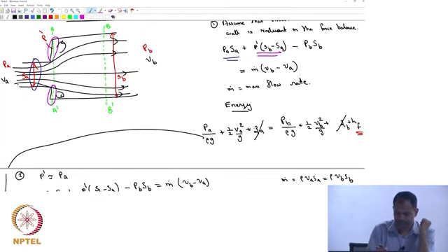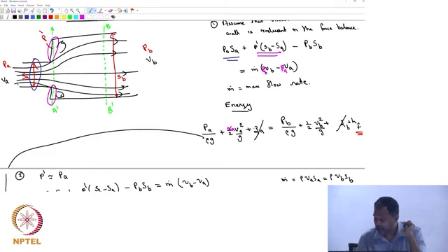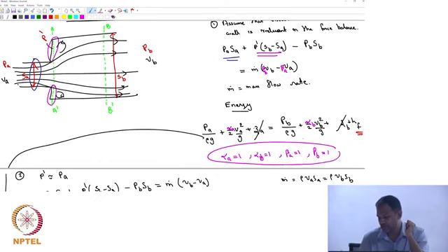There should have been a factor of beta B, and a factor of beta A, that should have given us our actual momentum flux, and here I should have had an alpha A and an alpha B. We have really said alpha A equal to 1, alpha B equal to 1, beta A equal to 1, beta B equal to 1. So, the calculations are better when these things are closer to 1, the ones which we have derived.